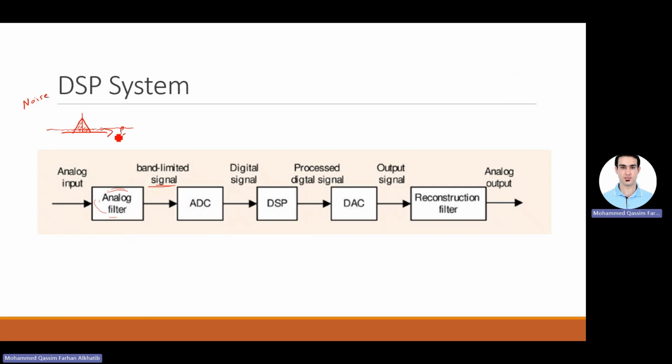So to make sure that I'm focusing on the desired signal, I usually apply a certain filter to the signal before doing any processing. That's what we call a band limiting filter, and that's what the analog filter is. So one reason is to eliminate noise. Another reason comes from sampling theory. Assume that I have a signal here that has the same response I drew there, and I did sampling. So basically I have a train of pulses.